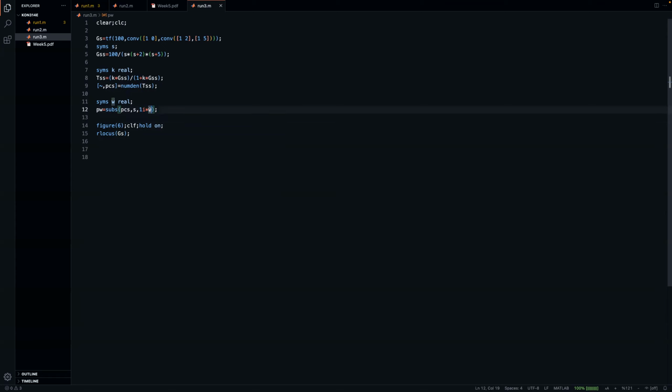The only thing is I don't know where this crossing happens, so I have an unknown omega, but it's going to be j omega, and its symmetric conjugate will be minus j omega. So there should be a j omega pair that crosses through the j omega axis. And if it's one of the closed loop poles, it should satisfy the characteristic polynomial. It should be the root of the characteristic polynomial of the closed loop.